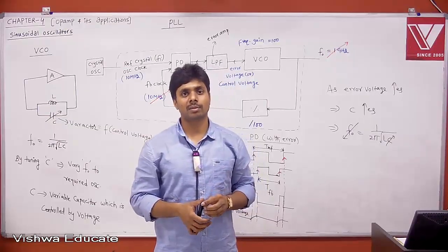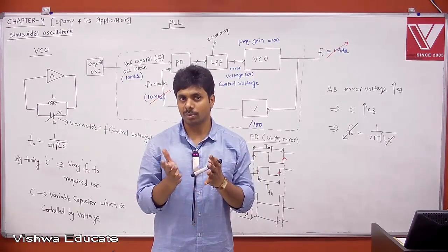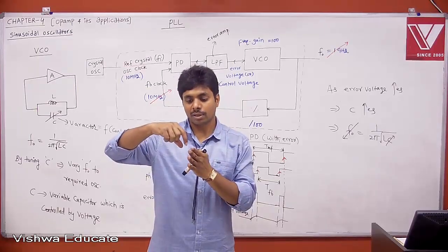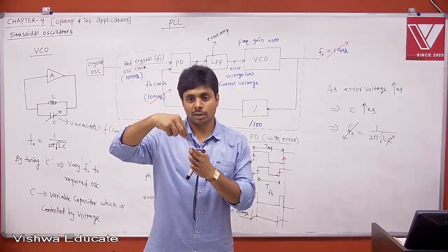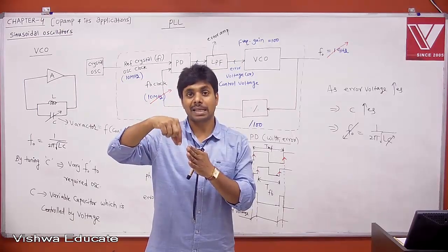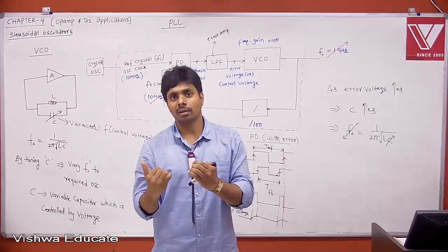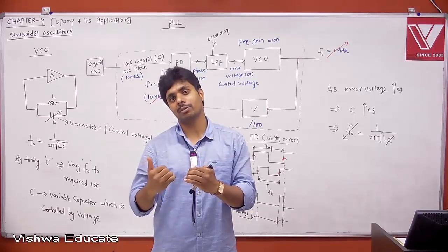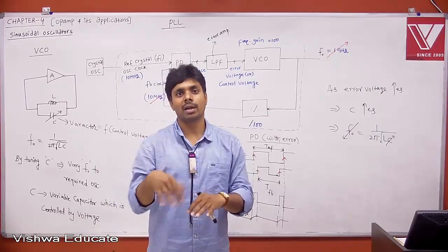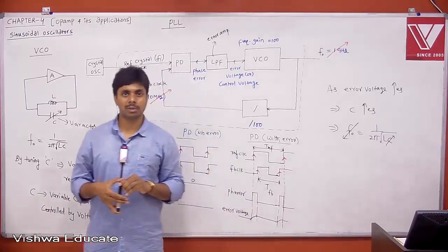If you take the 8085 or 8086 microprocessor, maybe when you did your microprocessor lab, did you see the microprocessor kit? On the top left corner of the microprocessor, you will see some metal can. That is nothing but the crystal, and then an amplifier. That open loop amplifier and the crystal will be there inside your microprocessor. Combined, that will give you crystal oscillations, which have the highest frequency stability of oscillations.